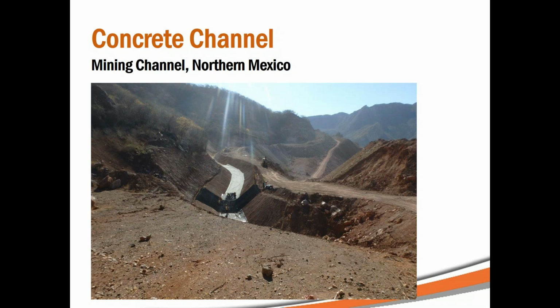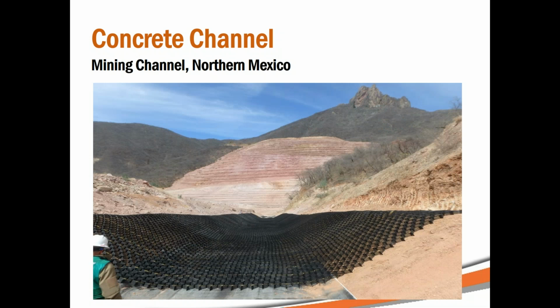So this was a project for a wastewater diversion channel from a mine in northern Mexico. The channel would be used infrequently, but expected flow rates were very high. The channel followed the contours down the mountainside, so there were naturally a lot of curves and corners. Those are the places where turbulent flow is most common along these types of channels, with turbulent water forces. So concrete infill was the right choice for this situation. A unique aspect of this project was the inlet channels, converging designs, formwork, reinforcement, and anchorage for each channel, the GEOWEB's entire channel network.